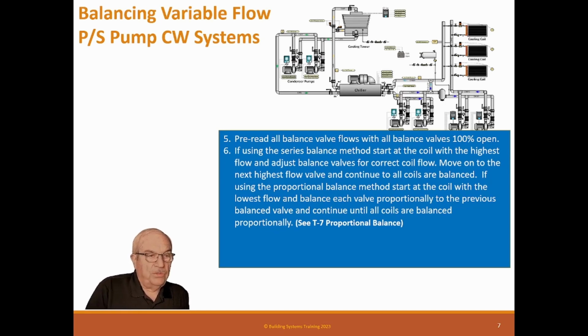Then when you get close, you have to look at where the valves are. If you have big valves left near the end, then you'll have a lot of opportunity to push that water right to the target valve. But if you have only small valves left, you don't have a lot of opportunity because a small valve doesn't push a lot of water downstream. So you have to think about that as you go, or else you're going to have to go back and rebalance a couple of times to get them correct.